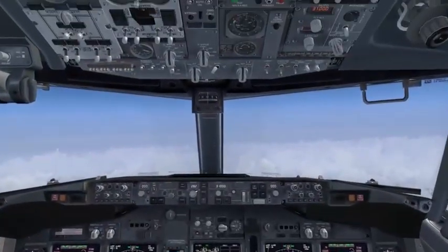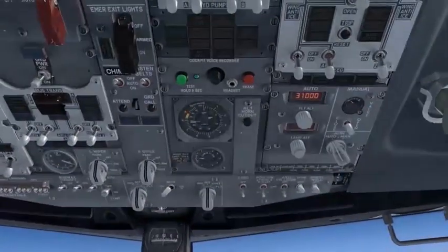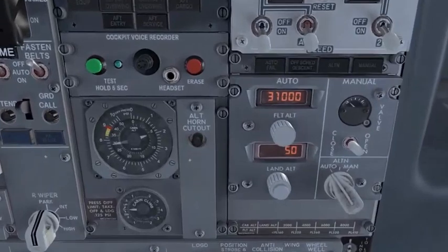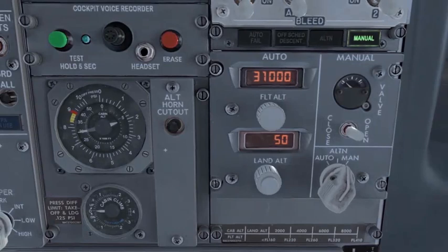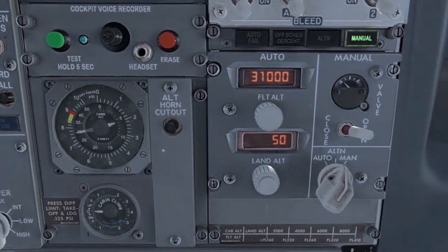Furthermore, the pressurization system may even be controlled manually, as we mentioned before. To do this, the pressurization mode selector must be changed to the manual mode. When this happens, the manual green light illuminates in the cabin pressurization panel. The outflow valve opening and closure is now controlled manually, and both automatic CPCs are bypassed.